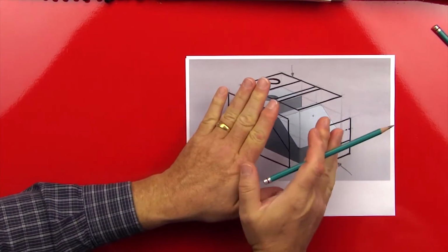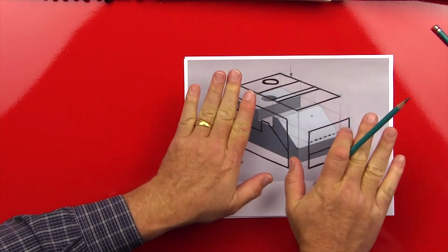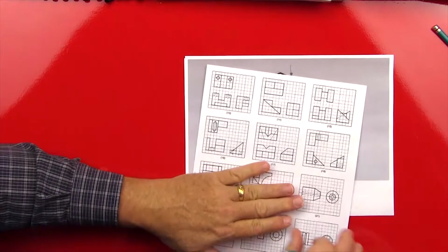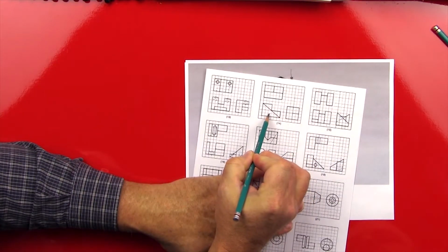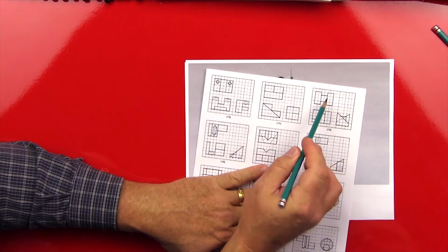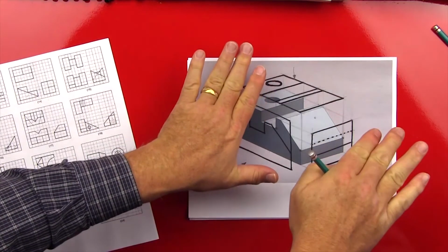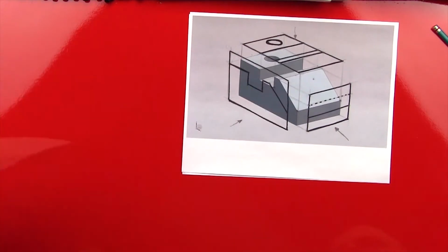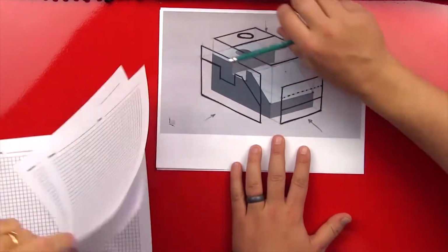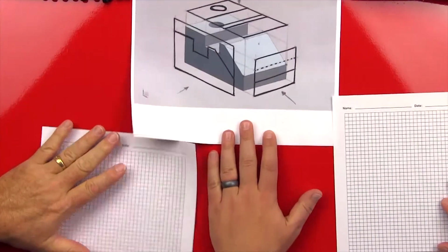So now what orthographic views do is they take these things and they open them up and lay them flat, and what you're going to end up with would be views like this. This would be the front view, the right side, the top view. A front view, a right side view, and a top view. Cool. And so we just need to open these up and lay them flat. Awesome. And to do that, I brought some graph paper, and we can very quickly come up with our 3 orthographic views.